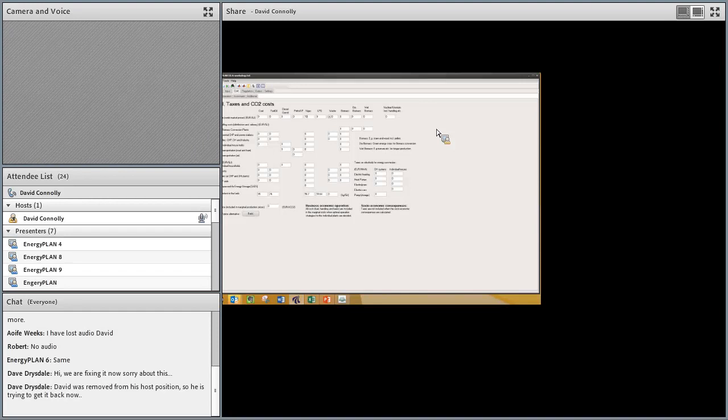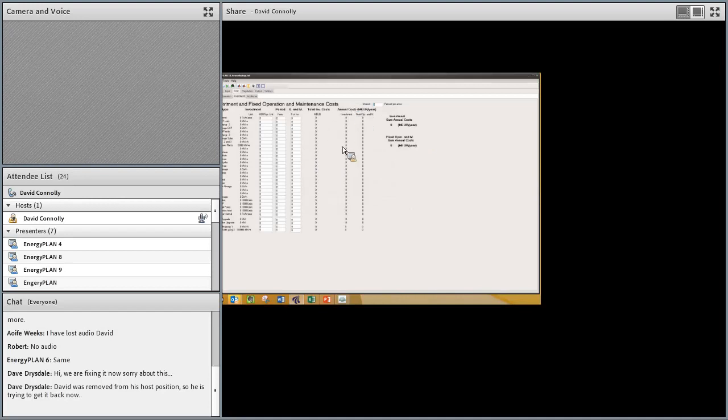The other thing I need to pay for are the power plants themselves, and that's done under the investment tab sheet, where you can see a lot of different options for different technologies and what their prices might be. In this example, I'm going to assume that the power plants cost approximately 1 million euro per megawatt. They have a lifetime of 30 years and an operation and maintenance cost of approximately 2% per year.